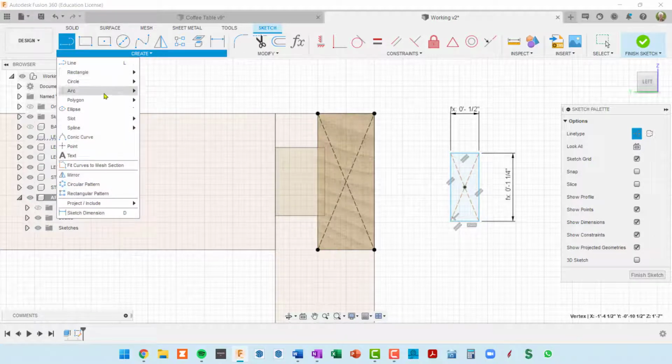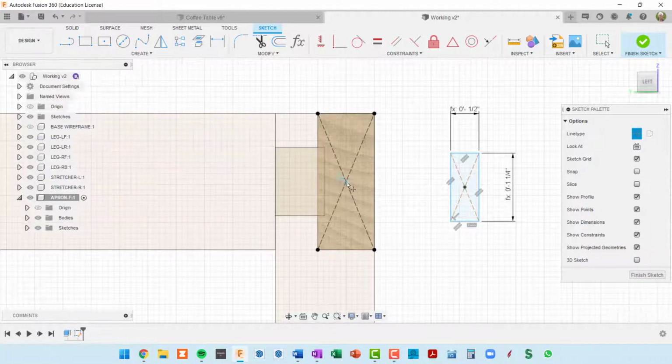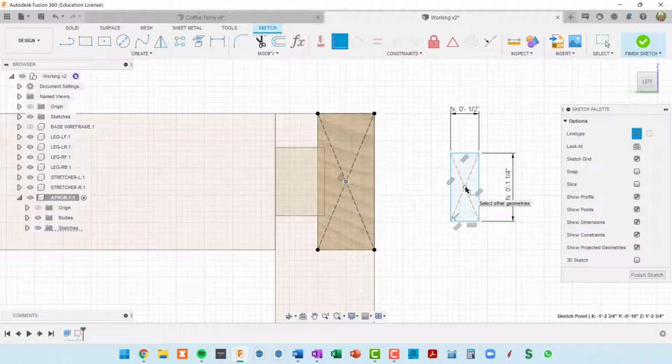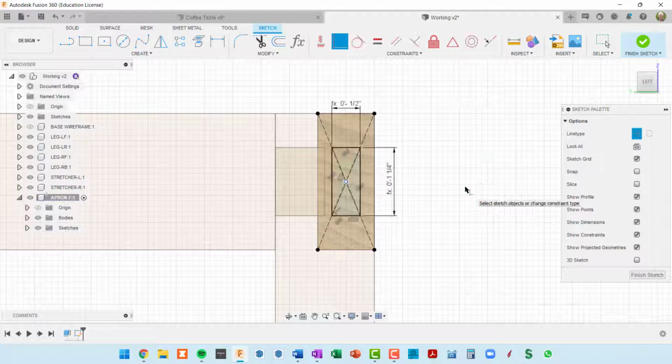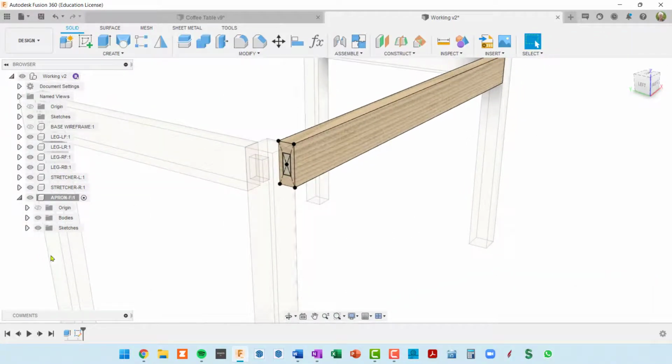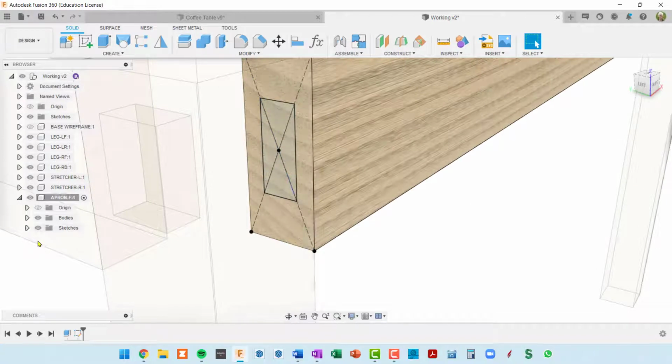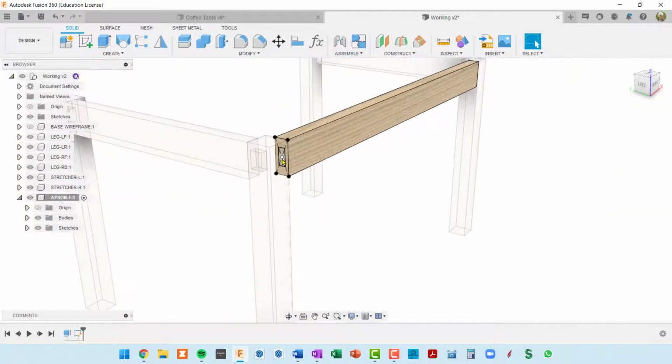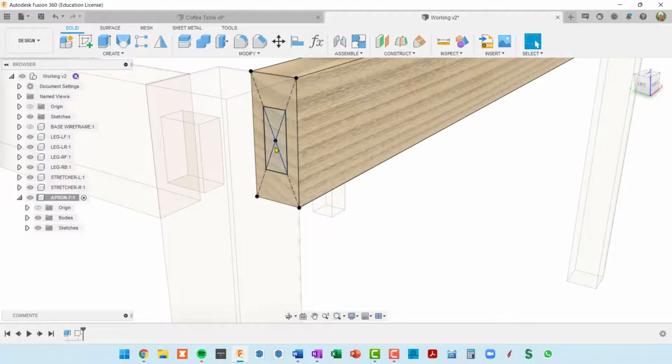And then I need to add that center point in at the intersection of the two construction lines. And then I can do a coincident. So I do my click to keep and click on this. This is going to move. So that moved to the center of the end profile of our apron. So we're done with our sketch. And this time Fusion leaves the sketch because it's a new sketch. If you create a new sketch, it'll leave it visible, figuring that you want to do an extrude or some other operation on that sketch.